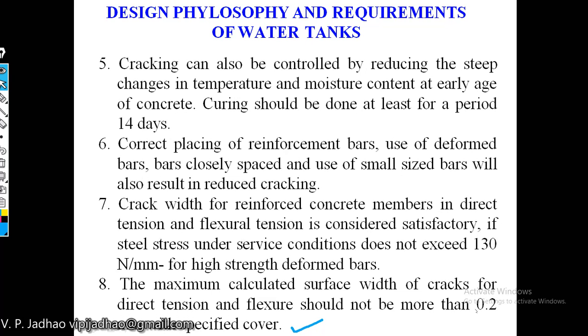Then the cracking can also be reduced by avoiding steep changes in temperature and moisture content. Therefore, we have to cure the concrete used for water retaining structures for at least 14 days. At the same time, correct placement of steel reinforcement, use of deformed bars instead of mild steel bars, and closely spaced bars should be used to reduce the cracking, because if cracks are present in the water retaining structure, it will be subjected to risk of leakage.